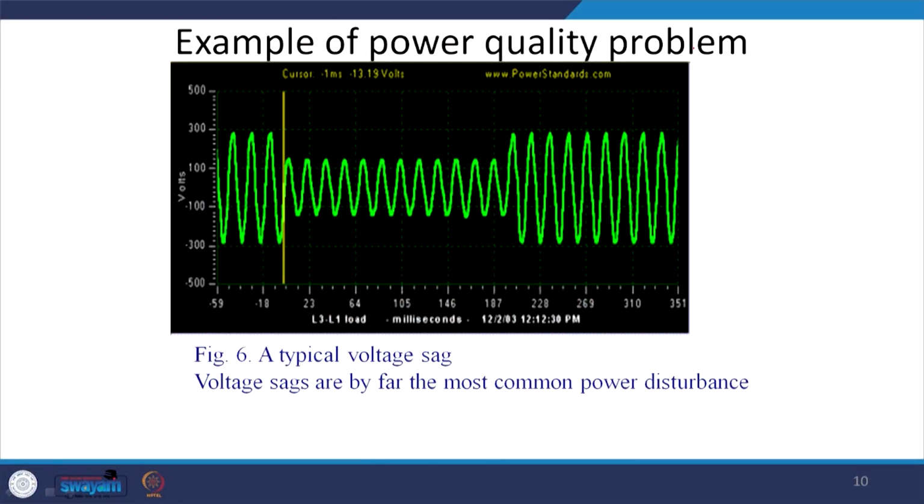I am giving you an example of our data. Look, this is an example of a power quality problem. This is a sag example. All of a sudden a sag comes, it may be that a branch of a tree is touching. The scale is in a lower range anyway, but for the high voltage it would be at the level of kVA, but some kind of voltage sag has occurred, and we will define what a sag is in subsequent classes. So, this is an example of a sag, and this is also a problem.